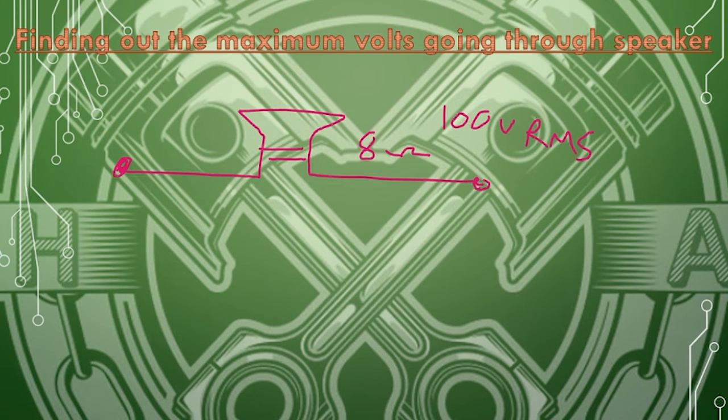Okay, so as I said, we are going to be finding out the maximum voltage that we can put across the speaker when it is in full operation. So to do this, we are going to need to square root. Again, you can put this in the calculator as you are watching if you do wish to do so, just so you can get a better understanding. So we are going to be putting the 100 there. We're then going to be timesing it by the 8 ohms, which will then give us an answer of 28.28 volts RMS.